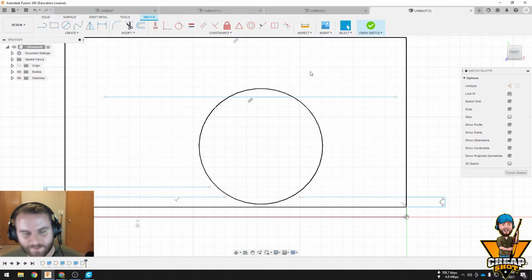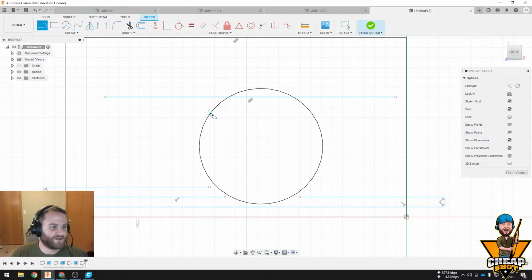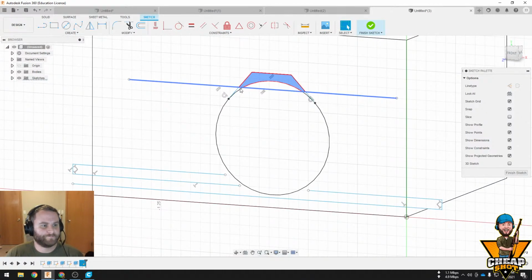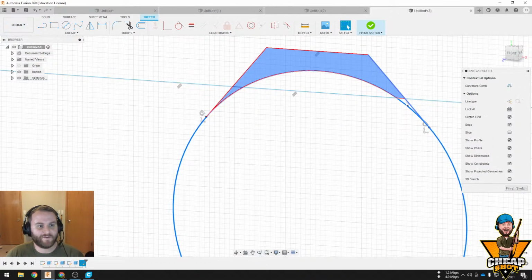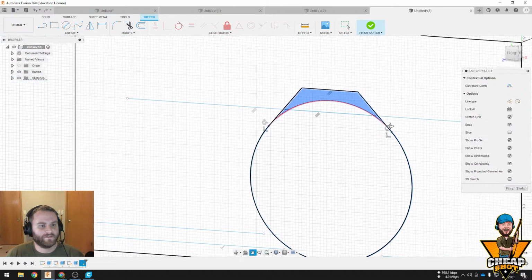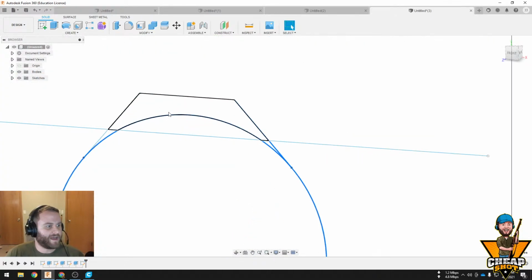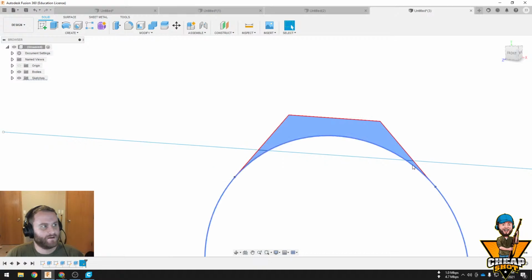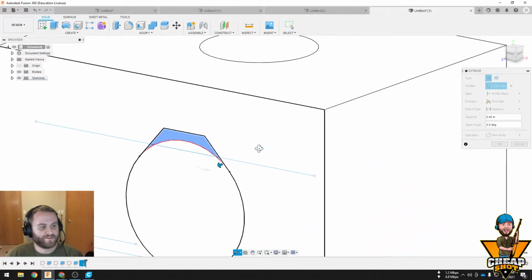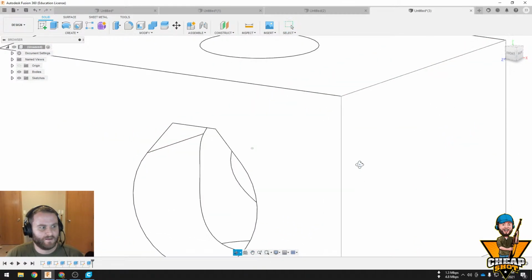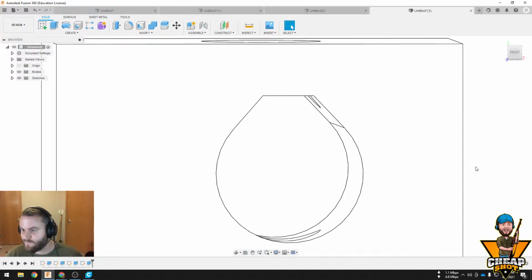So it's going to be absolutely horrible. What you should do if you're going to do a circle in this direction is give it a teardrop shape. You'll notice on the Hellfire or the Anderson lowers, they give it a little teardrop, and that absolutely makes it better for printing in the Z direction. It keeps it from being too small. Is it better to orient it flat around the Z-axis or vertical around the X or Y-axis?